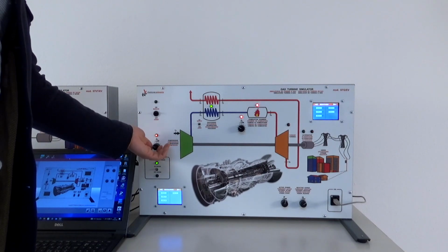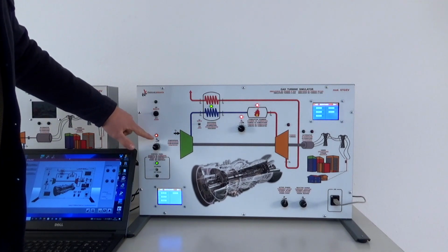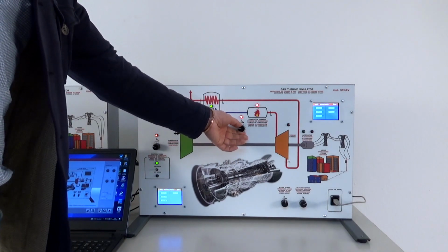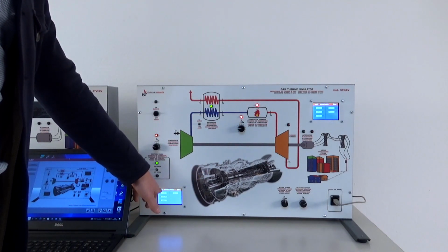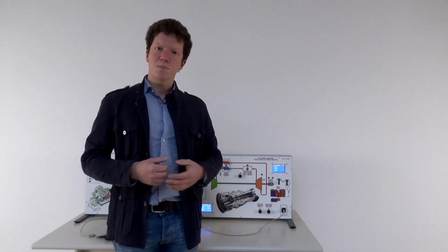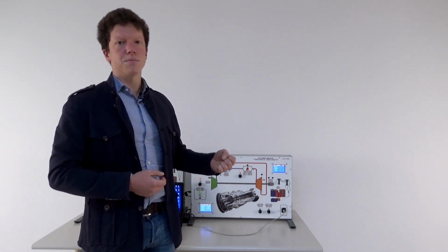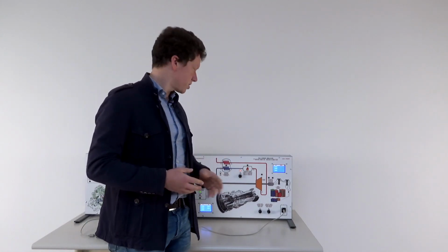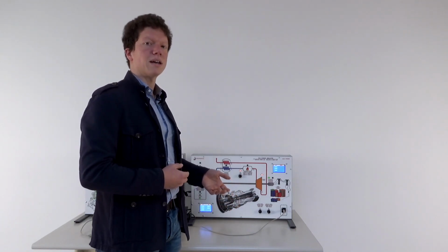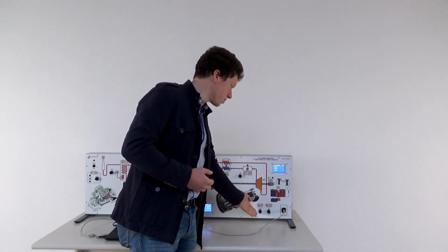By regulating the potentiometers, the students can simulate the different amounts of air and fuel in the turbine and see the output of the calculations in the various elements and in the attached software. The first part of the study is the on-design phase, in which the students can design the turbine according to specific initial parameters. Then they can toggle the off-design phase, in which they can simulate the request in active and reactive power by an external user.